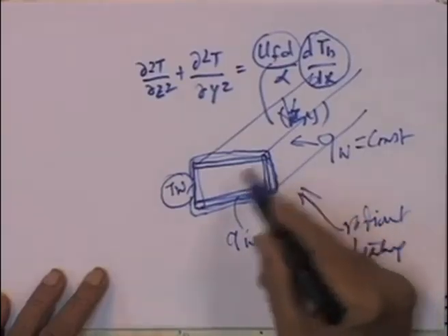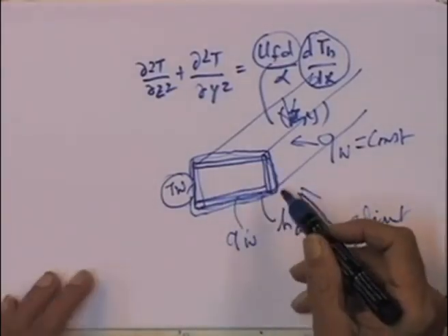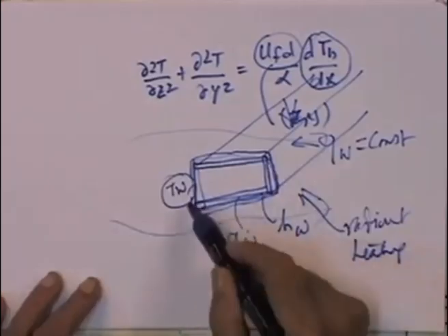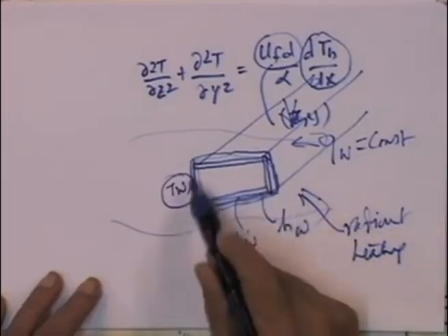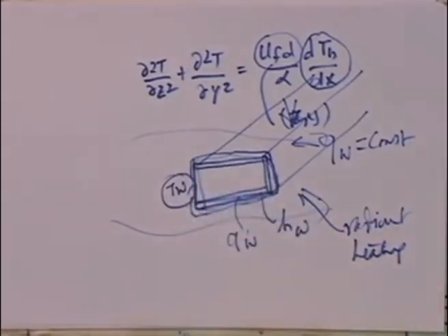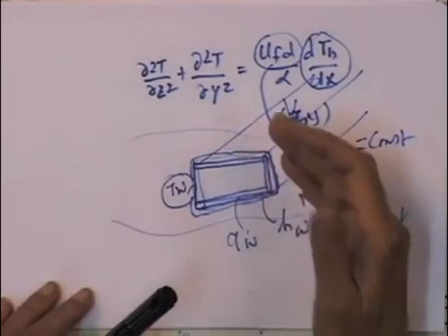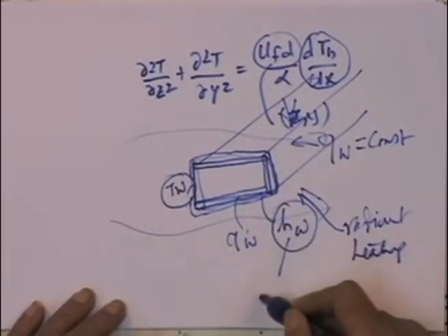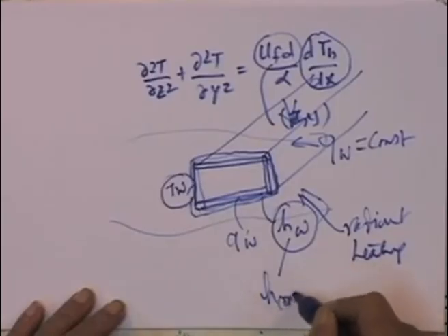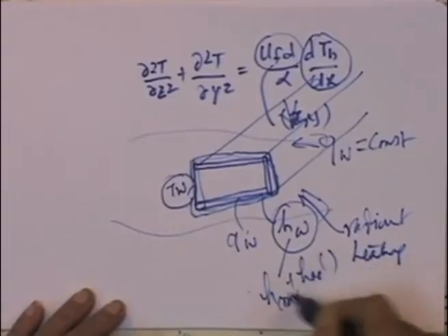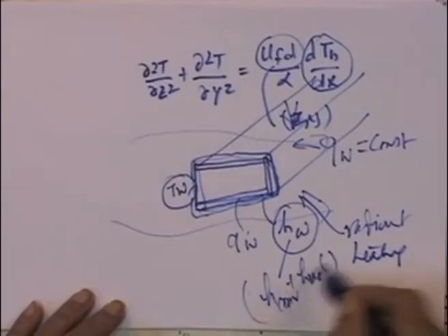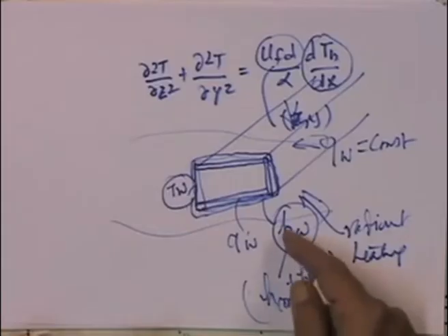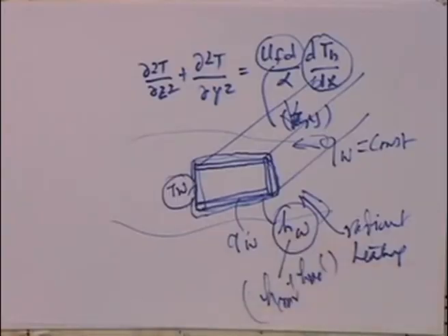and likewise heat transfer coefficient variation can also occur if there was, say, flow over this duct, in which case the heat transfer coefficient would vary along the periphery. This can be purely convective heat transfer, or it can be h convection plus h radiation variation. So, both types are possible, and effectively you have h w.